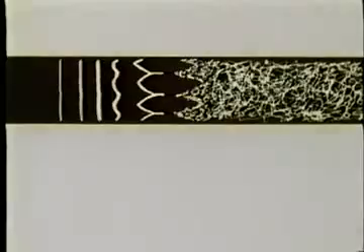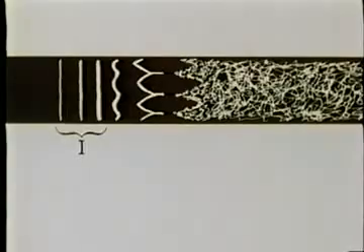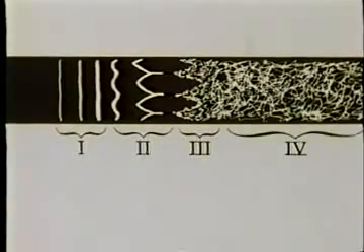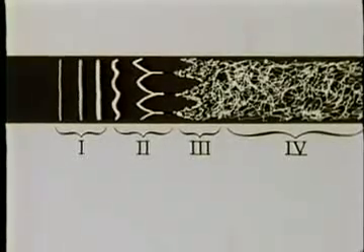First, we see the growth of nearly two-dimensional waves, the Tollmien-Schlichting waves, followed by the appearance and growth of three-dimensional disturbances associated with streamwise vorticity. Then turbulent spots can be seen. And finally, fully turbulent flow appears. Here, the exact position where growth of two-dimensional disturbances begins depends on random small-scale fluctuations in the flow, and therefore varies with time in a random way.